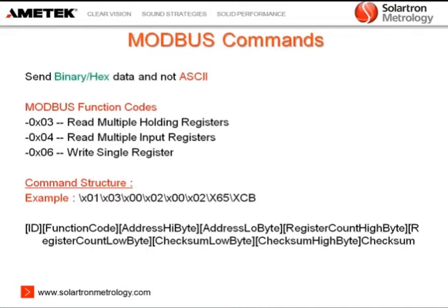So the MODIM interface module, which is at position 1 in the Modbus network, will use Modbus function code 3 to read multiple registers, because these registers hold my reading values, from a probe on the Orbit network, which is sitting at location 2. So in simple words, it's pretty straightforward. And at the bottom, you actually have things like the checksum byte and all the detailed information on how the command looks.